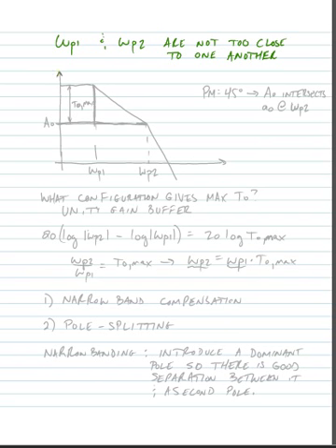If we have a two-pole system, or at least if we assume that if we have more than two poles, the higher order poles are much further away in frequency than the lower order poles, then we know that if we set the maximum loop gain such that the closed loop gain intersects the open loop gain at the second pole frequency, for instance, we're going to draw the open loop response for an operational amplifier, where we have two poles.